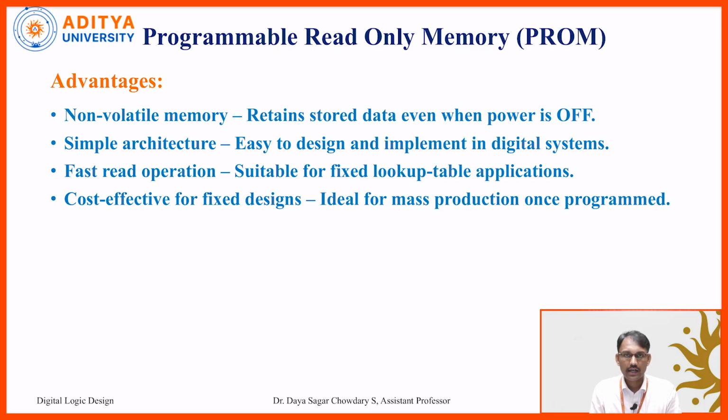Now coming to the advantages of this particular PROM. So non-volatile memory, as we know, because ROM contains the basic advantage, that is non-volatile memory. So it retains stored data even when power is off. And simple architecture, that means easy to design and implement in digital systems, and fast read operation, suitable for fixed lookup table applications. So lookup tables are used in FPGAs. Mostly we can observe lookup tables in the FPGA concept.